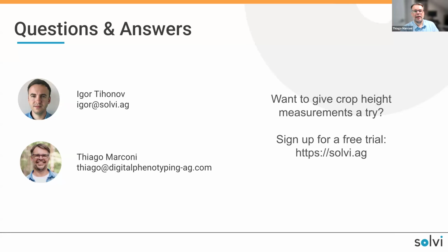So for very accurate height measurements, we prefer to use GCPs. Even with RTK, the accuracy of height can be a few centimeters off. Because this is research level data, we prefer to use RTK flight as well as GCPs.